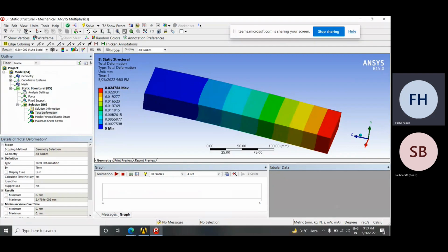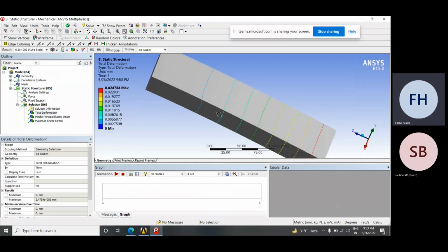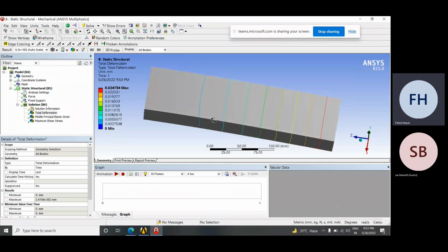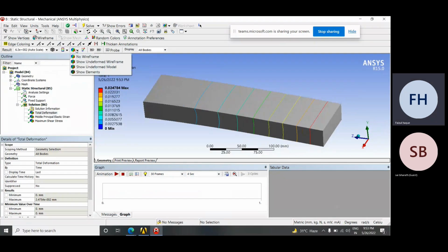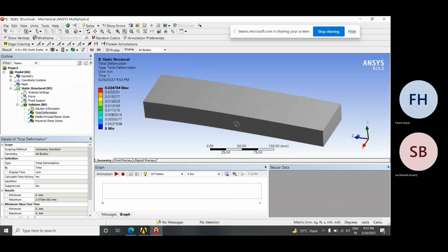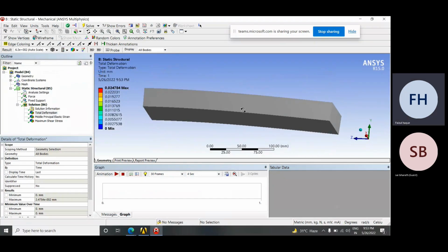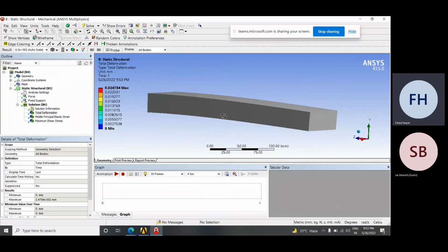If we select contour band, then the band occurs like the previous one. If we select iso lines, then the figure colors remain the same, and just the parameter lining part appears here. So this lining is known as iso line. And if we select solid fill, then no contour bands and no linings appear here.